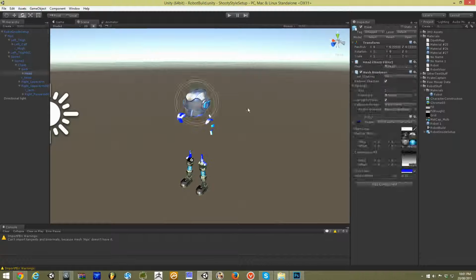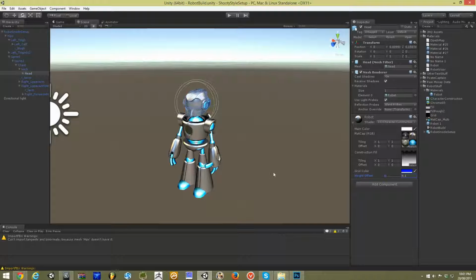In later tutorials, we'll be looking at how we can use this specific UV setup so that we can control other effects in our model that don't relate to having to look up textures, because there's a structure in which we can use this same UV coordinate system so that we can control things that include the actual structure of the mesh itself.